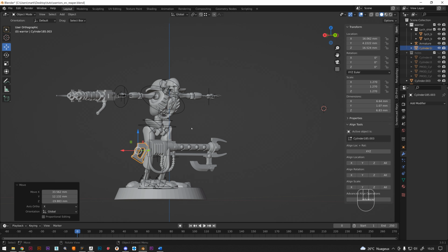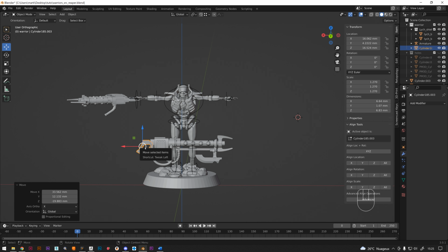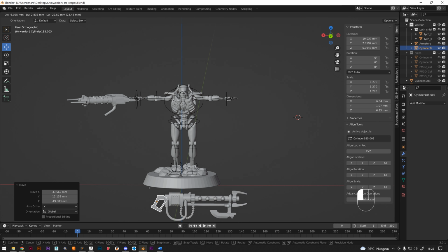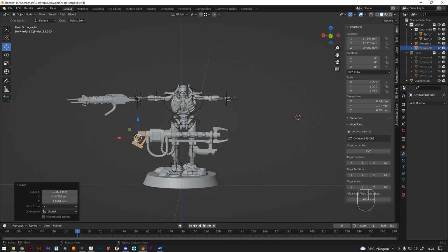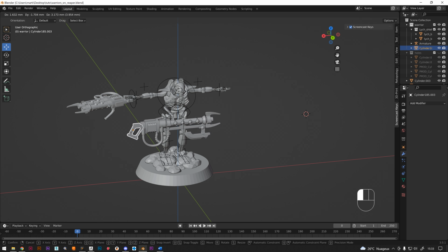Well, actually, the XYZ axes we're using here are just oriented differently. We no longer move the object along absolutely oriented axes, such as west or east as we have done so far, and that's why it's confusing. So what we're doing is moving the object relative to the view. So we can move an object to the top of the view, to the bottom of the view, or to the left or to the right of the view. But never in depth. Remember that a move in 3D is, paradoxically, made with 2 dimensions maximum. So when we use the small white circle, we say we are using the axes of the view orientation.